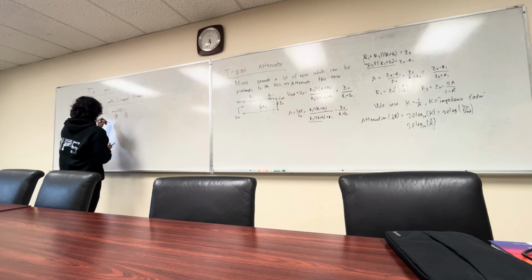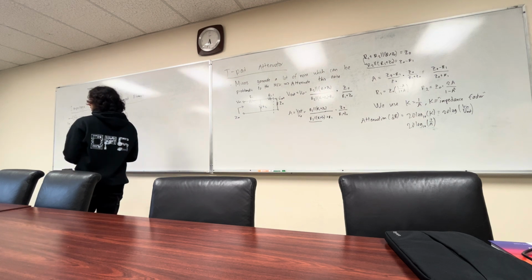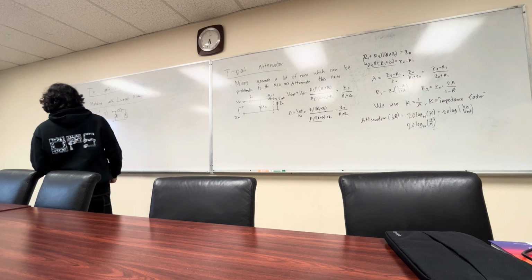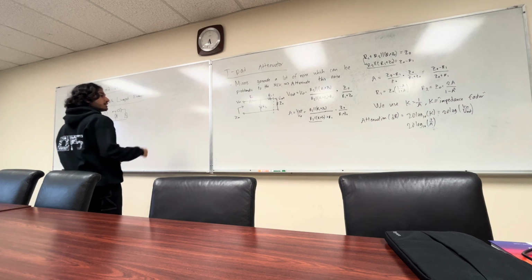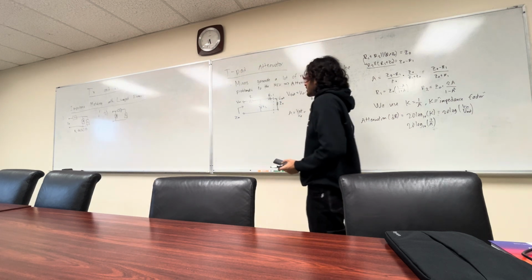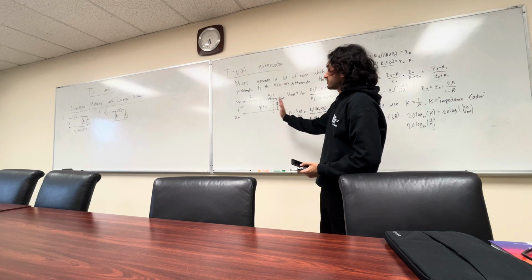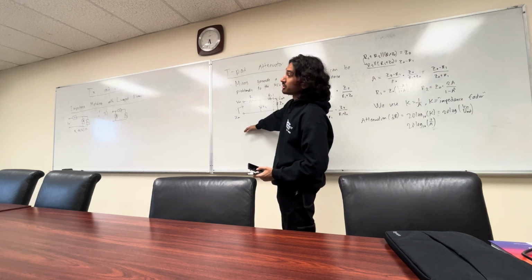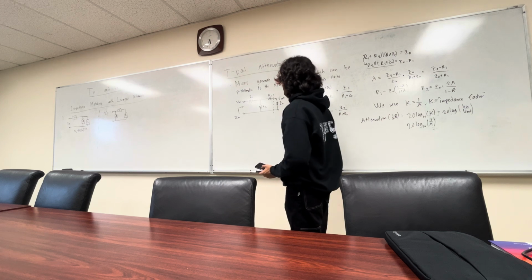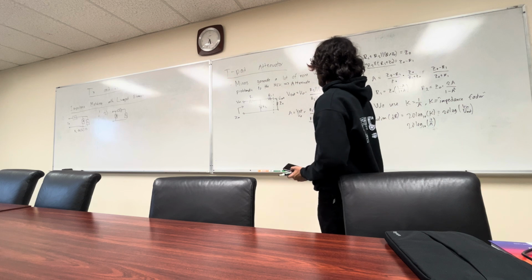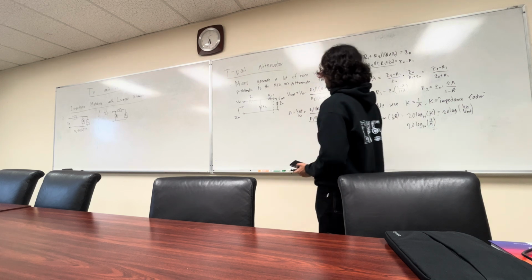Just a quick question. An attenuator, that doesn't affect the common mode, right? It does. I'll erase it. But effectively, ideally in your system throughout the RF chain, you have DC blocking capacitors for your amplifiers, such that in the signal path it is purely RF. In reality, you're going to see some DC level due to LO leakage, DC offset, and various other offsets.